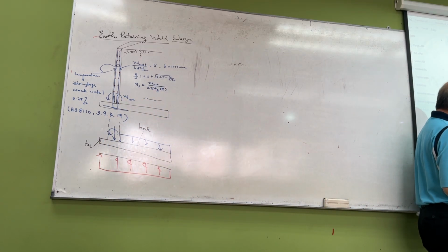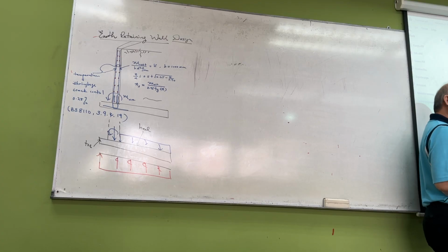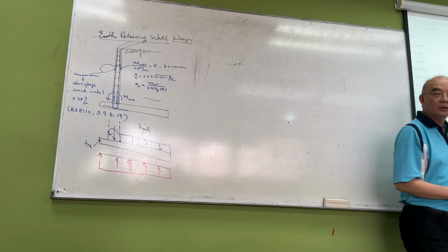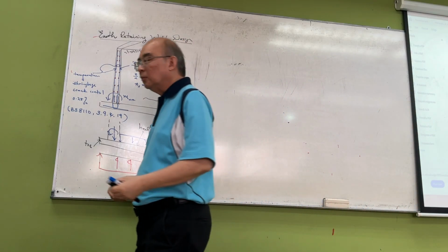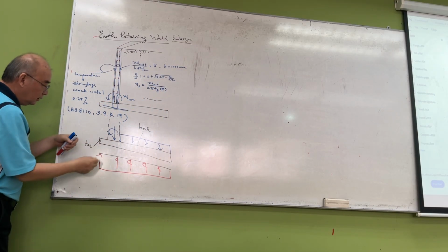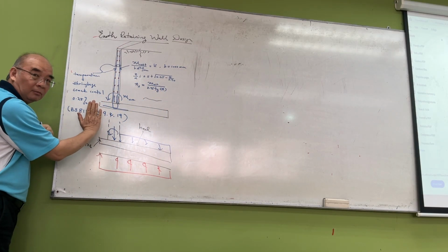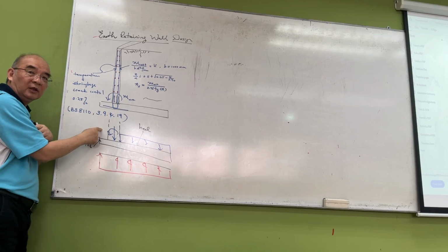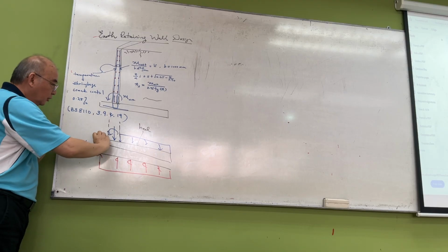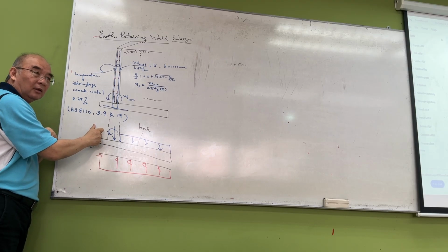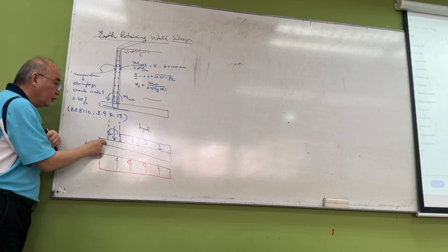So here we say a T12 at 200. The rebar is at the bottom. Why at the bottom? Because here you have this one pushing it up, and you don't have this much resisting. So this one is actually bending up like that, right? So bending up like that, that means the tension is on the bottom side.